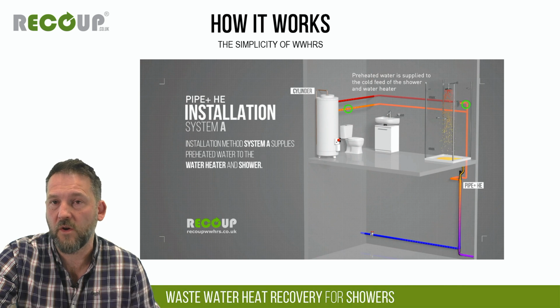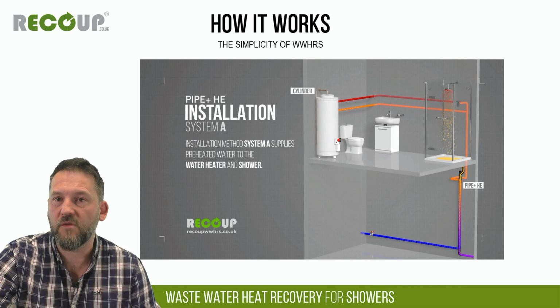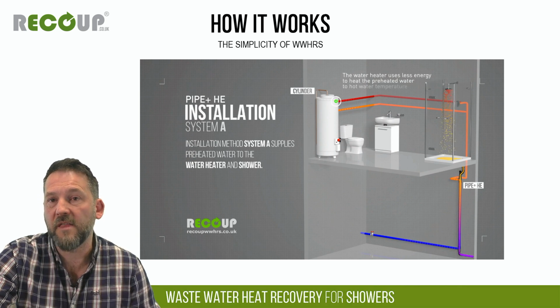So we're not interested in the grey water, we're not harvesting the grey water, we just want the heat energy. As the shower's switched on and warm waste goes down the drain, cold water comes in that would normally be feeding the cold side of the shower mixer and replenishing the hot water tank. That is then fed onto the other side of the heat exchanger, goes around the outside of the heat exchanger